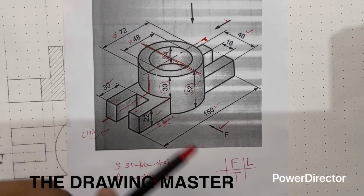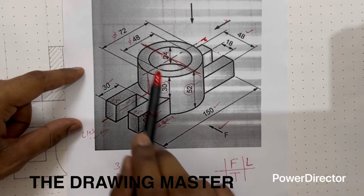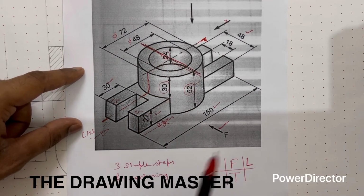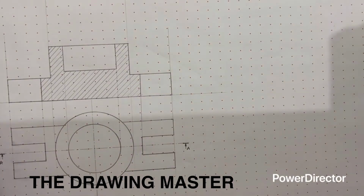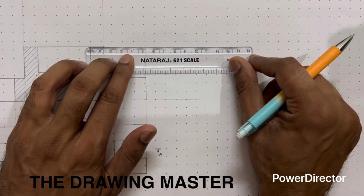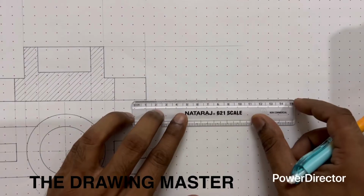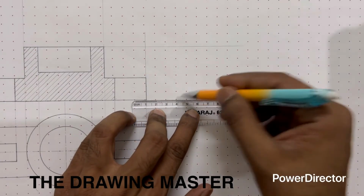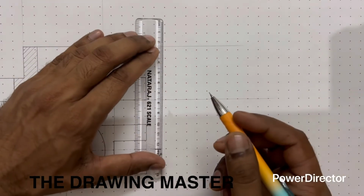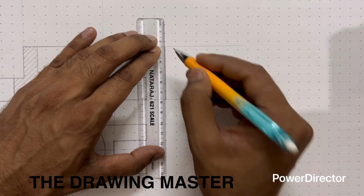So what would be the sectional view? It's very simple. From the side view, you have to simply draw the outline of the object. The outline will be 72 and 52. 72 is the diameter and 52 is the height. So let's draw the outline. You can take the projection from here for the height. We have projected the height. This is height 52.